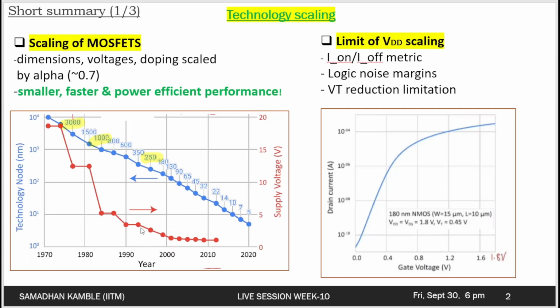At the same time, if you scale a particular technology and make it smaller, we are able to make more transistors, that is, double the number of transistors for the same power dissipation. The sizes have reduced, and because we saw that the power dissipation has reduced, effectively we can say it increases the number of MOSFETs by the same amount.